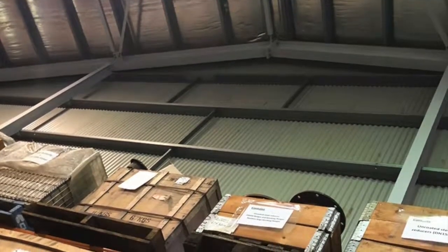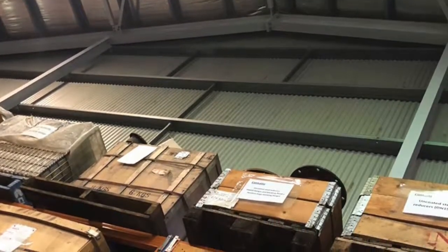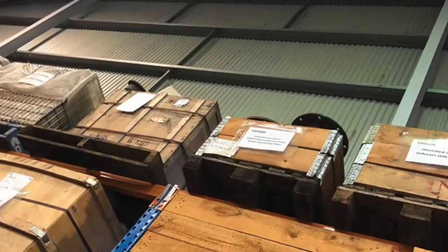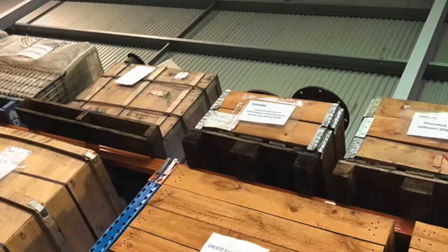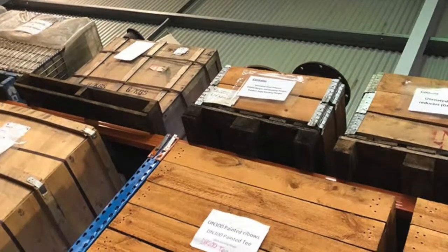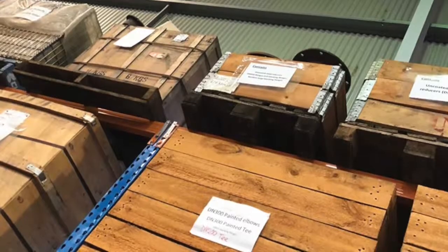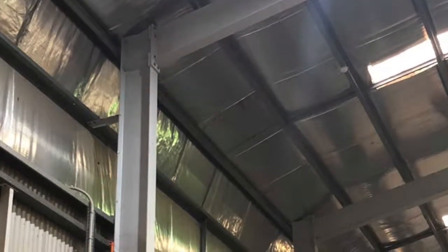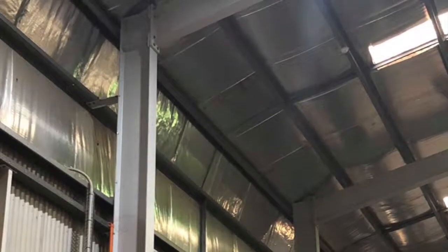The main structural element that the columns and beams support are the rafters, purlins, bracing and sheeting of the roof structure. A rafter is a sloped structural component that is used to support the roof decking and associated loads. They are most commonly C-sections that vary in size and are joined together at the ridge with an apex connection and at the column with a knee connection.